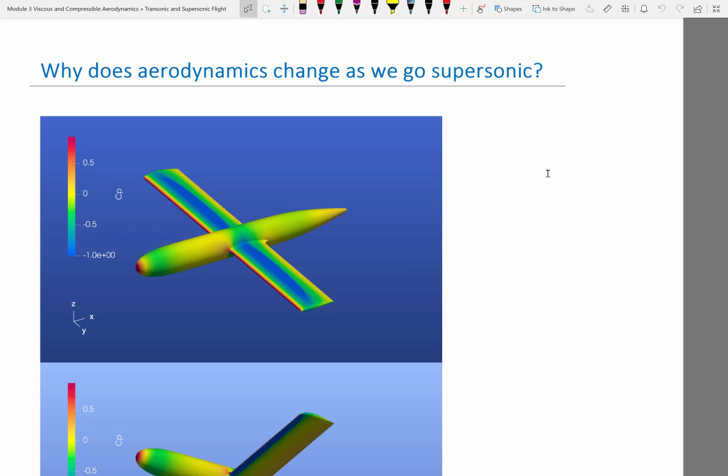And in particular, you can observe how the transonic and the supersonic behavior would be dramatically different from what I'm showing here, which is a very conventional subsonic geometry with a straight, non-swept wing, and a much thicker airfoil. I think this is using the NACA 2412. Basically the same airfoil like Cessna uses, okay?